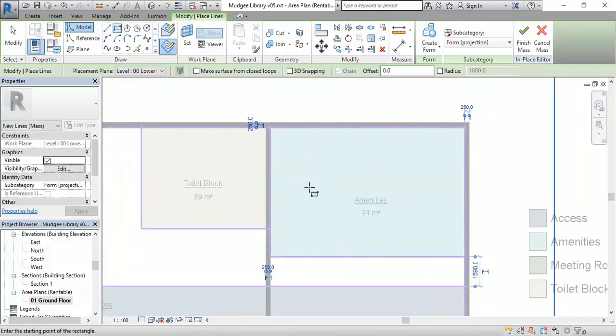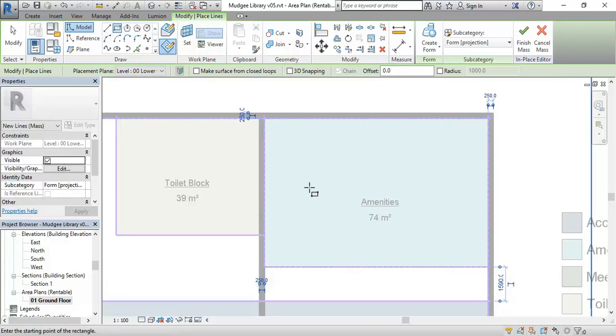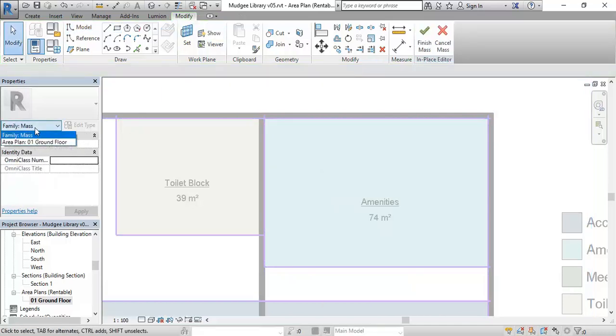Any idea why? So when you see that message, you should be thinking about view settings. The reason it can't see it is because of the settings in this view. That message is telling you the object's been made, usually just fine, but we can't see it, that's all. So before I go too far, I'm going to now just change in properties to the view properties, which you can always do using this option here.